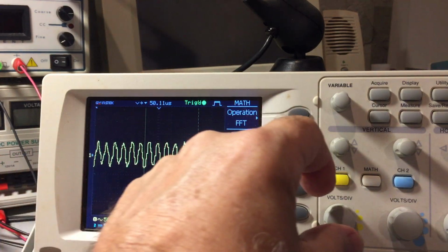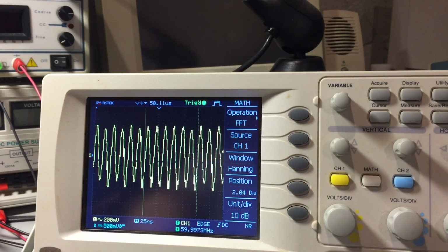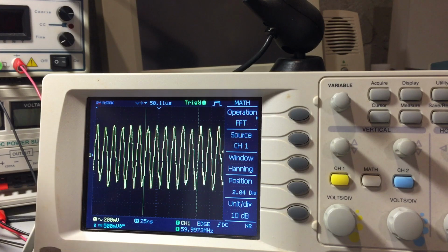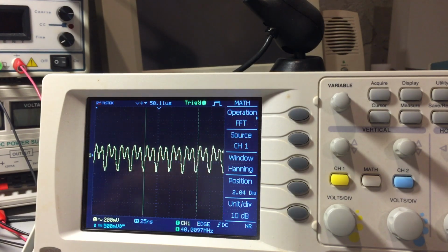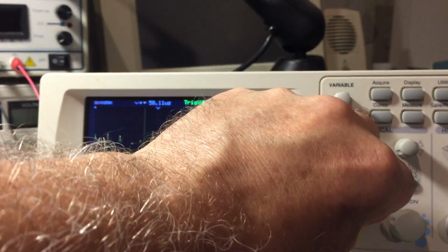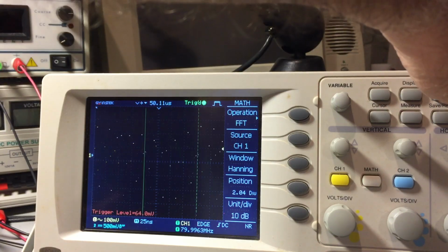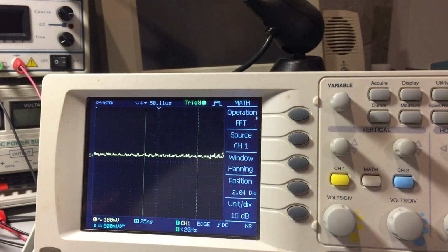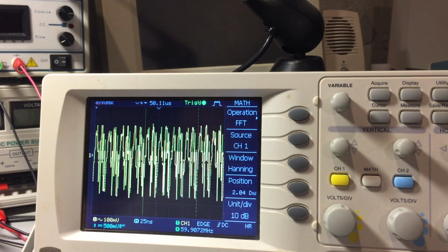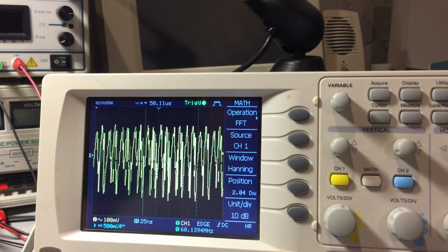and probably have to increase the voltage per division. Yep, you can see 60 there, and let's go ahead and try 40. Maybe we need to raise the amplitude a little bit, perhaps, and try to re-trigger on that. No. So yeah, about 30 megahertz is the limitation. It'll go close to 100 megahertz if you put it on a perforated board. It will work at a much higher frequency and respond much better.